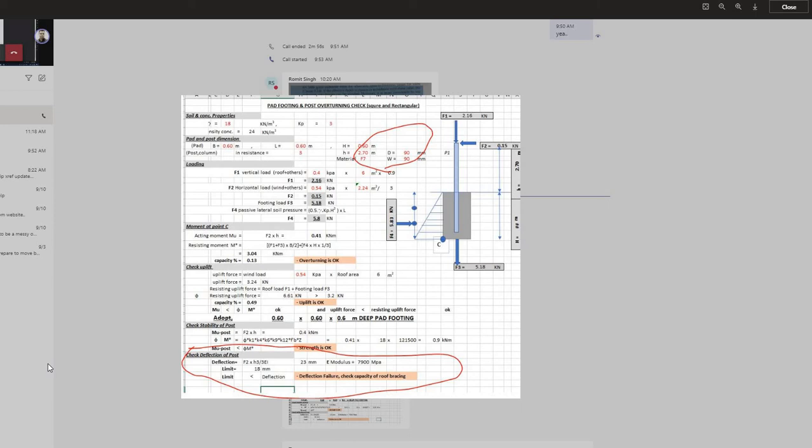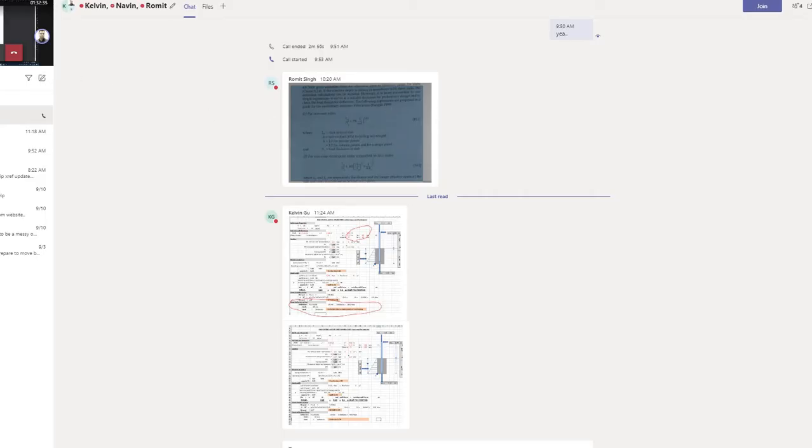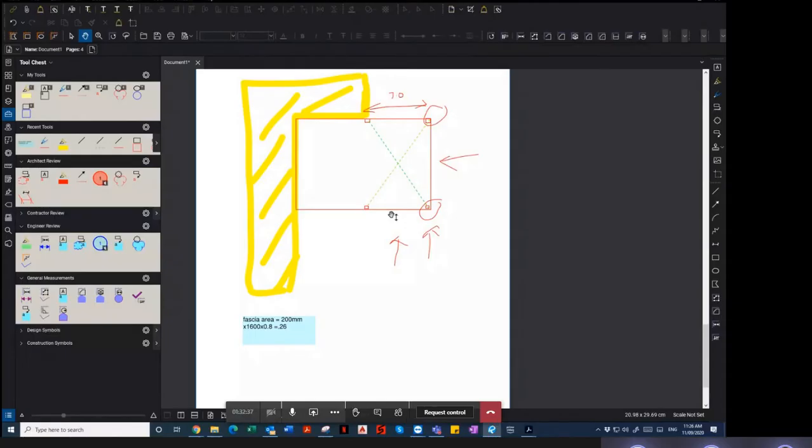Moment looks fine. In some instances, when we are in a situation like this, it's ideal to use a 100 by 100 post, and at the same time put bracing in, like the step bracing. Step bracing helps us to transfer forces from the outside force over here back into the house.